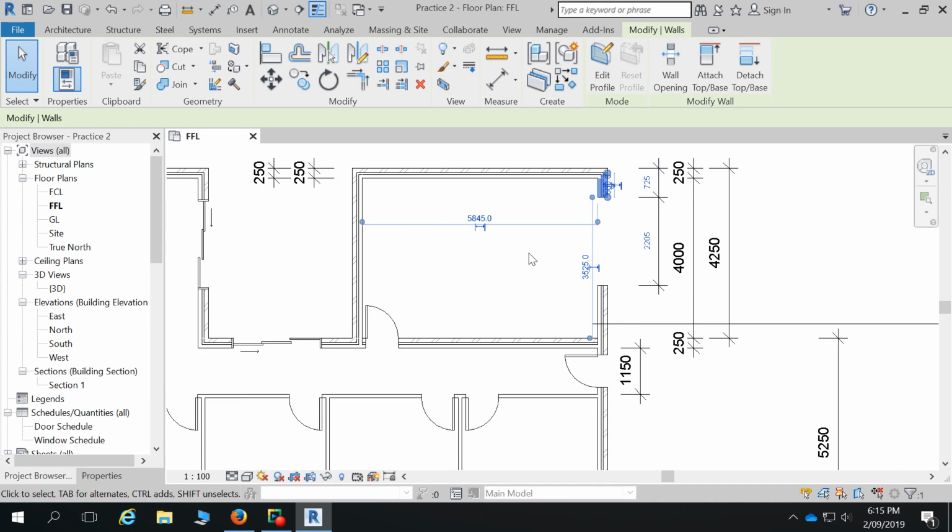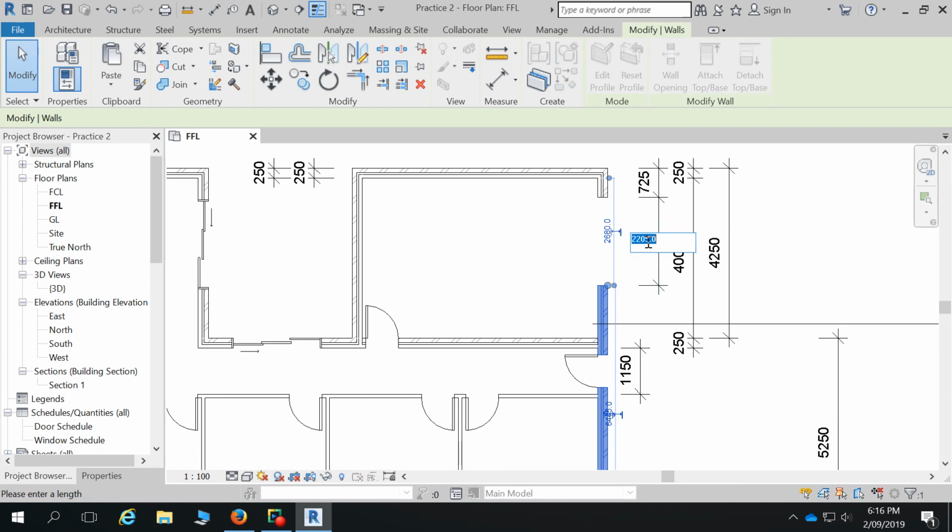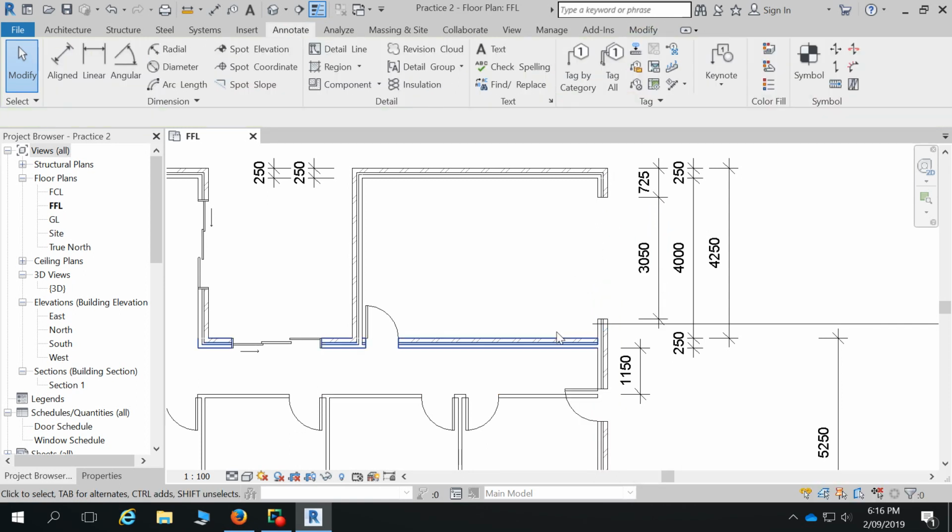What I need to do is actually select the next piece of wall, which I'm going to shorten to make this dimension. Because that one's not blue, it's not going to be changed. And this one now is going to change this end from here, because that's its only reference point. That dimension was 305? Yep. And you can see it comes across to there.